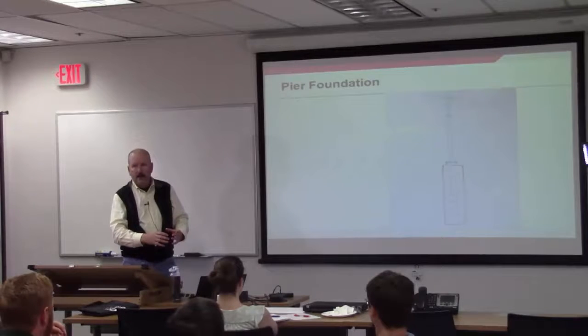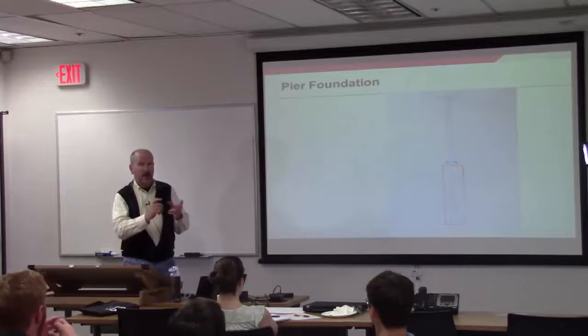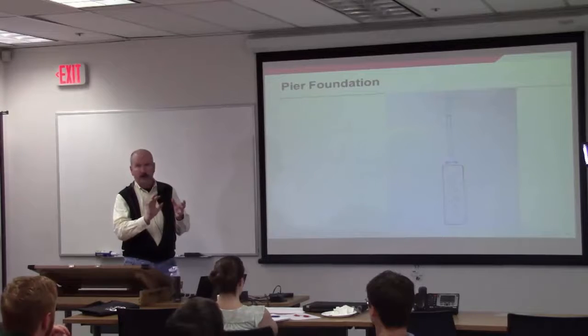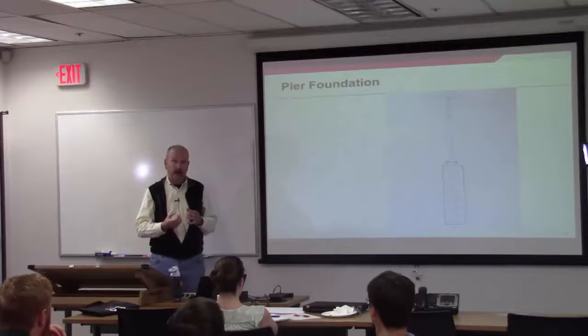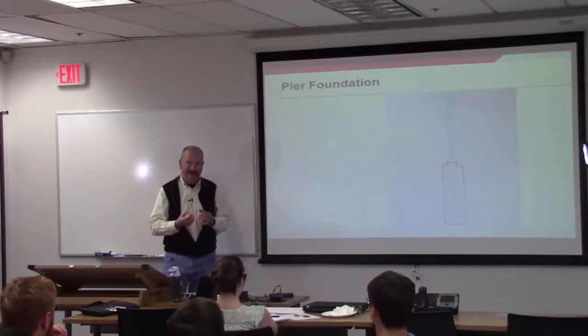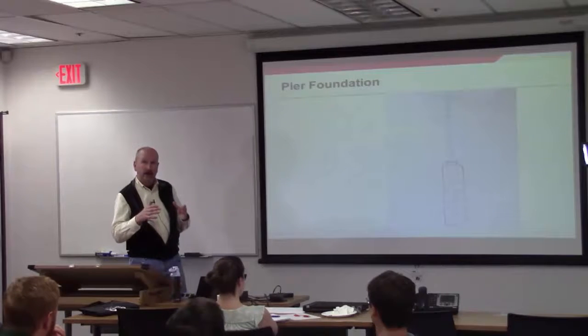So anyway, going back, this is what you'll end up with. You'll lower the cage down into the hole and get it in precisely the right location, and get the anchor bolts, and very important, you get the anchor bolts precisely located, and then you fill it up with concrete. And you're going to finish the top of it so it looks nice and professional and brand new. And then there are some other aspects at this point, making sure you don't have any voids in the concrete, because air doesn't have nearly the strength capabilities that concrete does. And that's really how your pour goes.